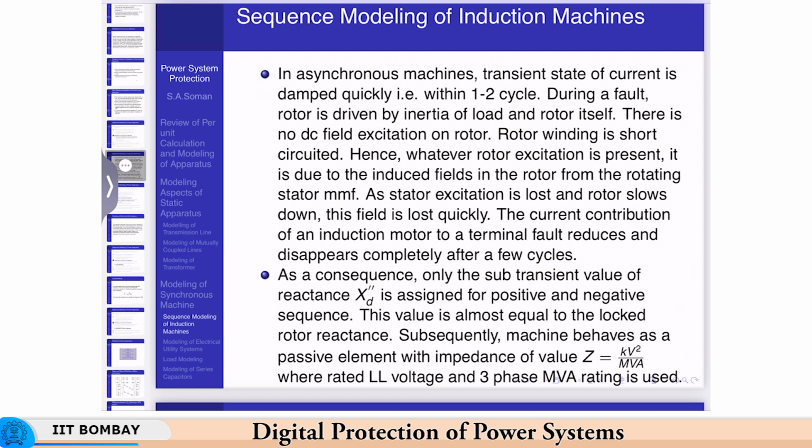Now this is the reason that the fault contribution from induction motors is sometimes ignored. We can consider it if we want a very accurate representation of the fault currents, but even if you ignore it, the loss of accuracy is not too much. If the contribution has to be considered, then only the subtransient value, the X'' or the locked rotor value of the impedance needs to be considered, in which case the short circuit contribution of the motor is roughly of the same order as its starting current, which is 5 to 6 times its full load current. Also many a time the contribution of a group of motors is lumped together and considered as one single motor without loss of accuracy. This is how an induction motor is represented in fault studies.